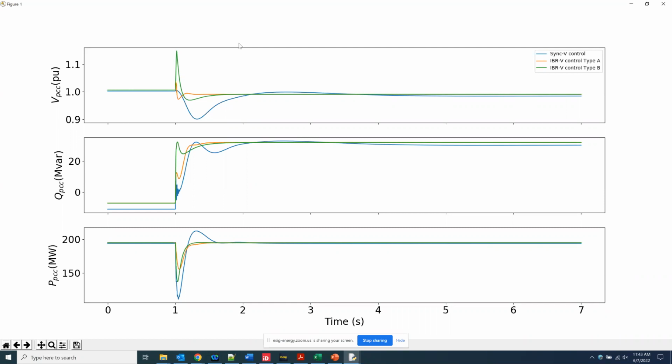On one of your earlier slides, you showed grid forming versus non-grid forming. Non-grid forming or grid following had a phase lock loop. But performing fast voltage control doesn't exclude having a phase lock loop. I'm a little bit confused because there are certain manufacturers of wind turbines that have a fast voltage control of the terminals of the wind turbine, and then they have a slower plant control. It's a hierarchical PI control.